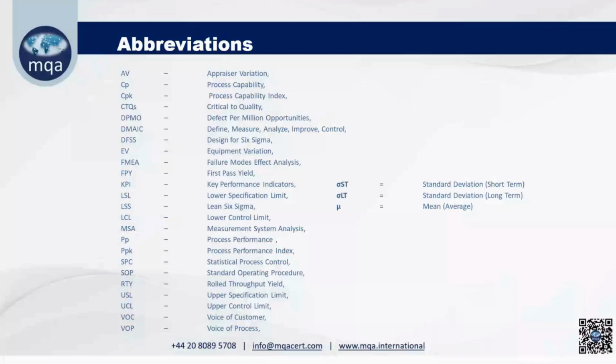Our specification is plus minus 0.1, so what is our tolerance? 0.2. 0.2 upon 6 sigma. Sigma is standard deviation. And what is CPK? CPK is upper specification limit minus X double bar, the average, divided by 3 sigma, or X double bar minus lower specification limit upon 3 sigma.